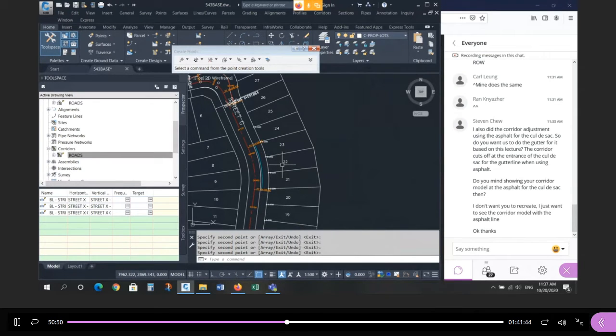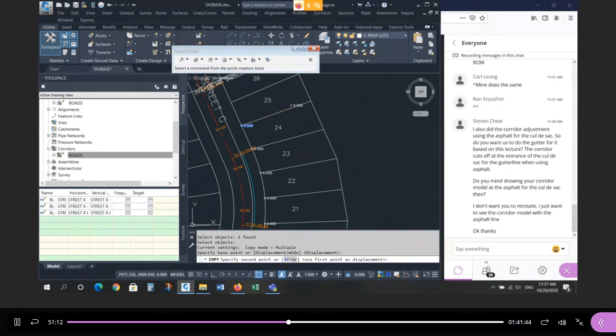Remember, we had different groups with different layers. We're going to do the exact same here. So I need a layer for the front lot corners, that's the proposed elevation. I need a layer for the rear lot corners, that's the existing elevation, and I need a group for each, because you're going to have a different style for each. So you put elevations at the front, you put elevations at the back, same technique. You put points at the back.